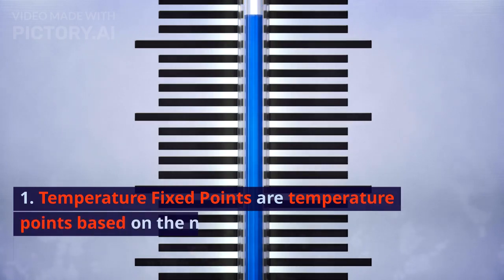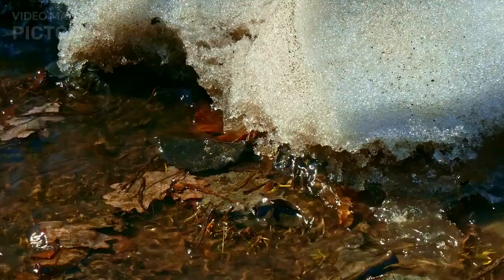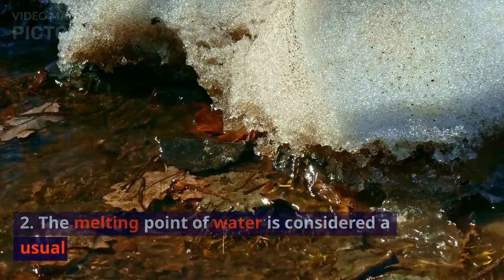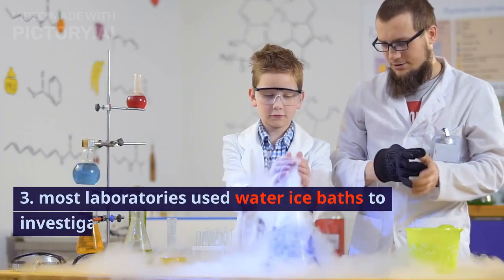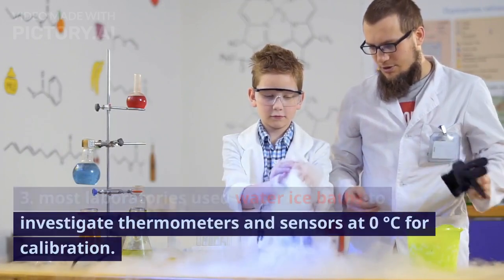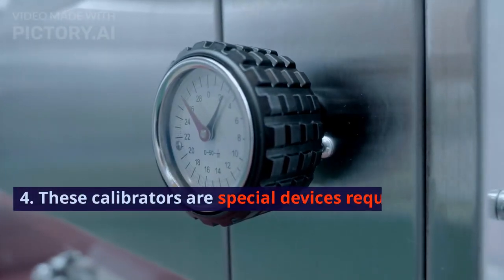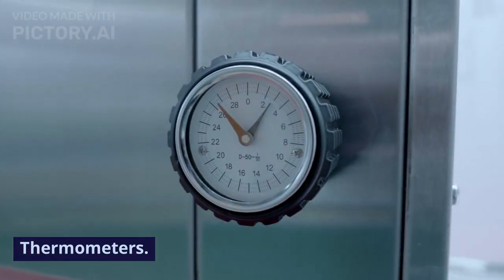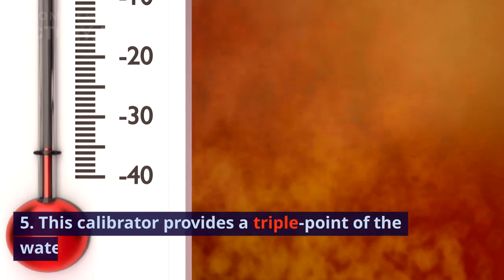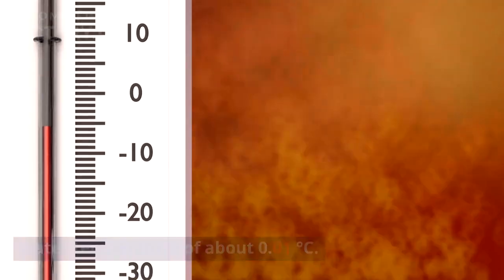Temperature fixed points. 1. Temperature fixed points are temperature points based on the natural freezing and melting temperatures of pure materials. 2. The melting point of water is considered a usual fixed point. 3. Most laboratories use water ice baths to investigate thermometers and sensors at 0 degrees Celsius for calibration. 4. These calibrators are special devices required for calibrating standard platinum resistance thermometers. 5. This calibrator provides a triple point of water temperature of about 0.01 degrees Celsius.